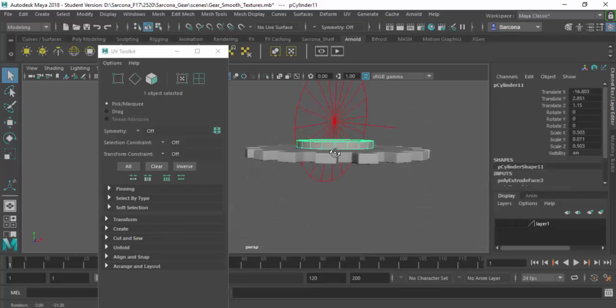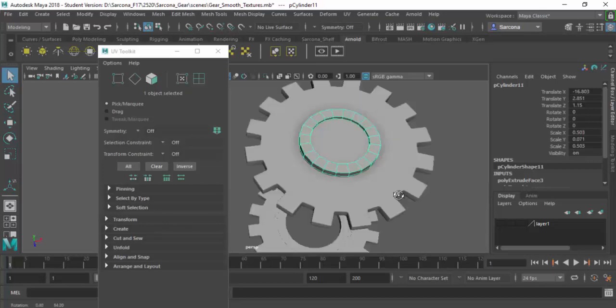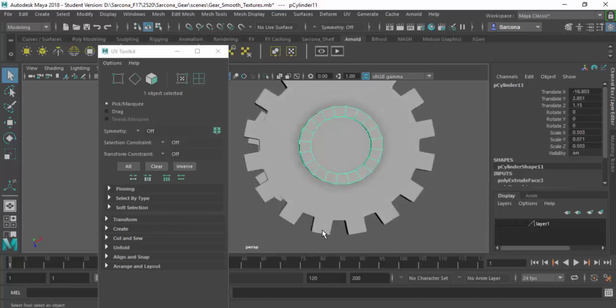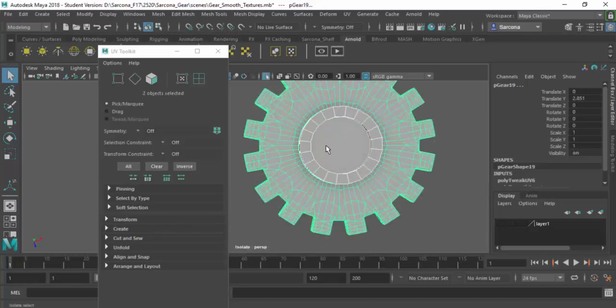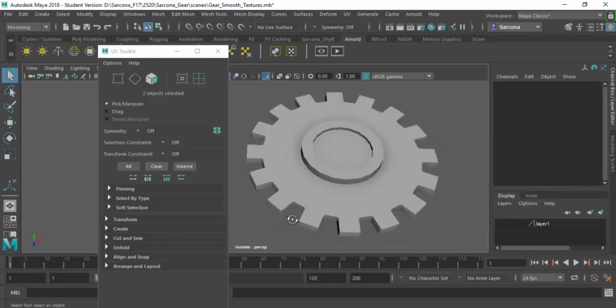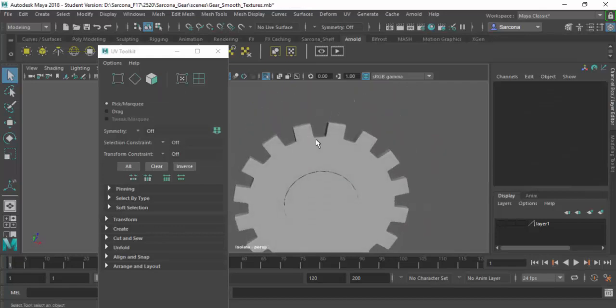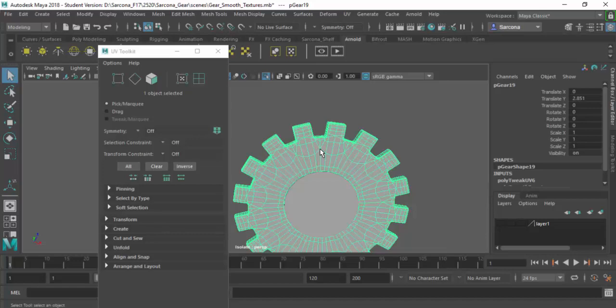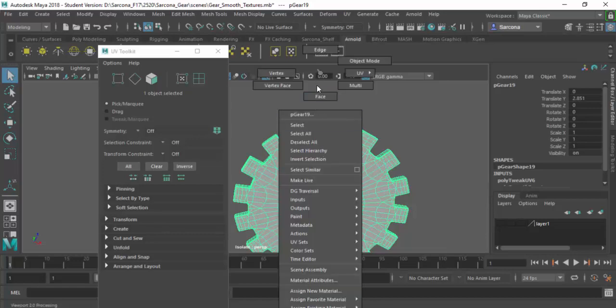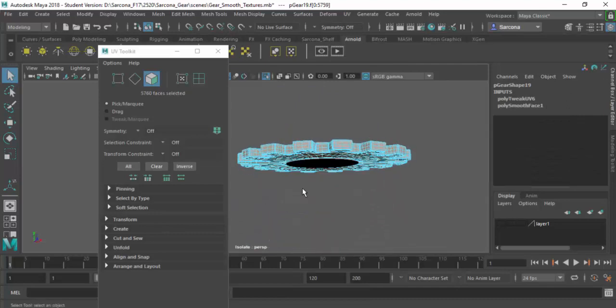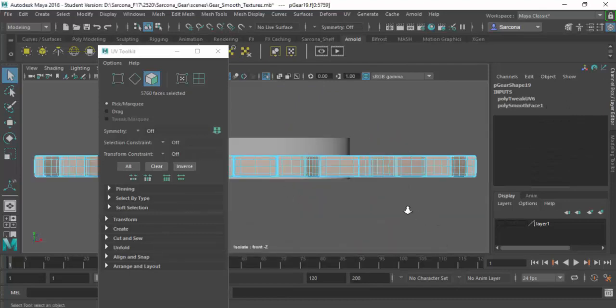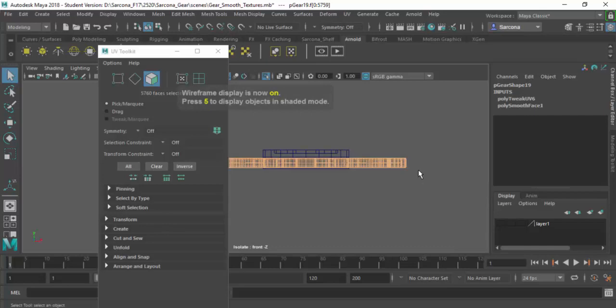Now the other thing to consider is what is actually being rendered. Don't waste your pixels on stuff that's not going to be seen. So if my shot is from this view, let's just pretend I'm working with these two items. Am I going to see any of this stuff? No. So why have it, right? It's just going to take up space inside of my UV editor. So I basically want to delete anything that's not going to be seen. So if I go into my side view, I just marquee that.